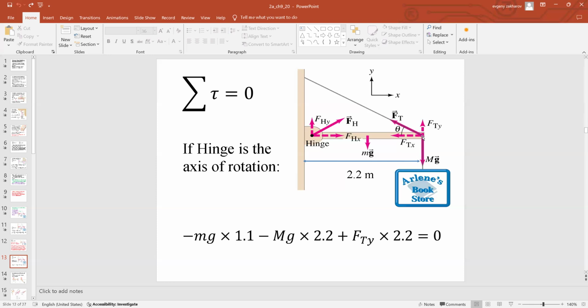However, it's only the tangential component that we're really looking at, because your x component, see how the line of action would cross the hinge and you would not get any rotation from this component of tension. Only the y component is the component that creates rotation.